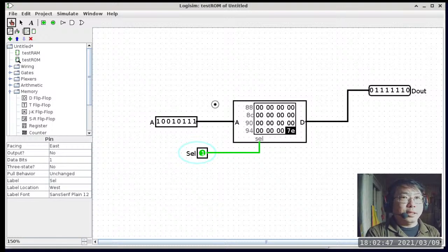Then we have to say, okay, when we specify something bigger, do we specify the least significant part first, or the most significant part first? So that's why the TTP does not have endianness built into the processor architecture, simply because everything is 8-bit wide. The address is 8-bit wide, the data is 8-bit wide, the registers are 8-bit wide, the ALU is 8-bit wide, so everything is only 8-bit wide. So there you go.